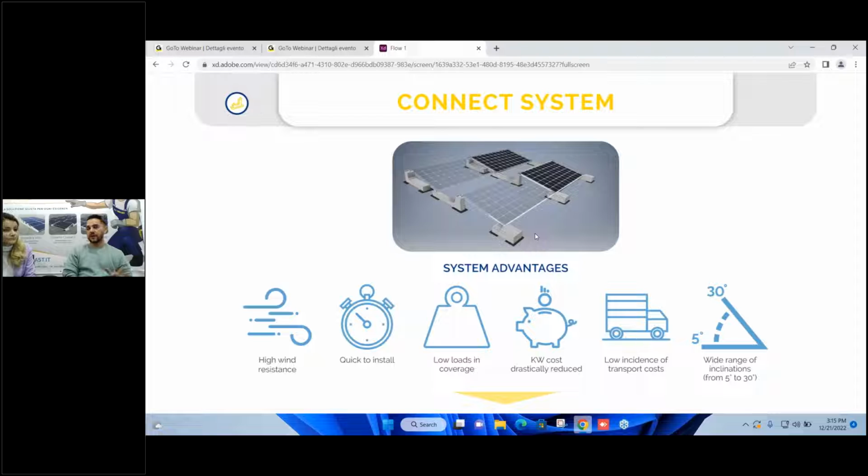Those that are known for having less weight on the roof because of the material they have can still end up heavier than our ballast, which is all concrete, because they need to put ballast plates on top of it, and a lot of accessories go with our structure. The weight is distributed. They put a lot more weight; it's necessary. So even if it's 15 or 20 kilograms per square meter, it's still resistant.